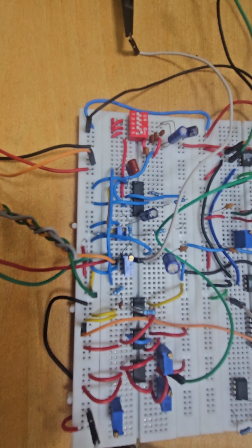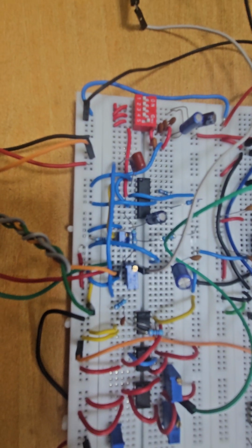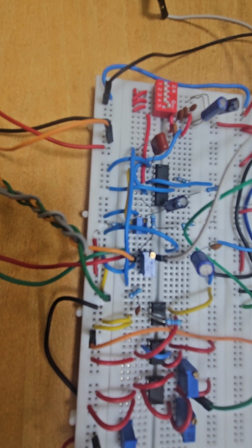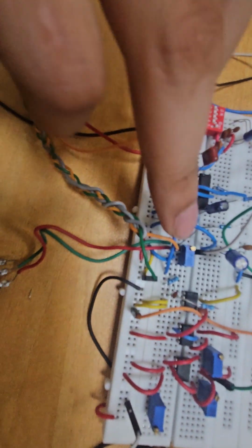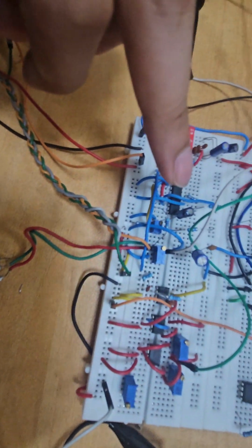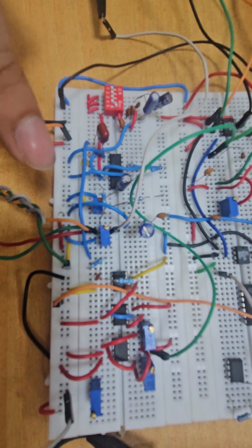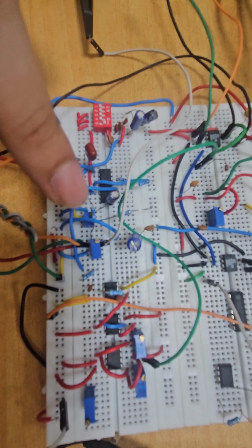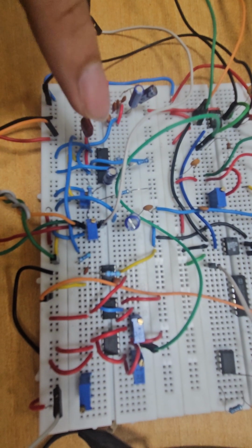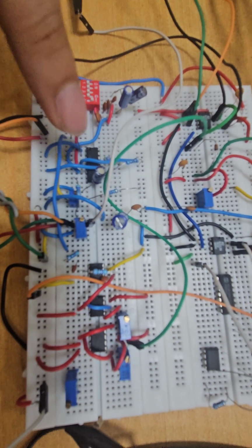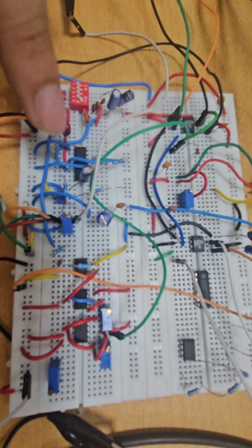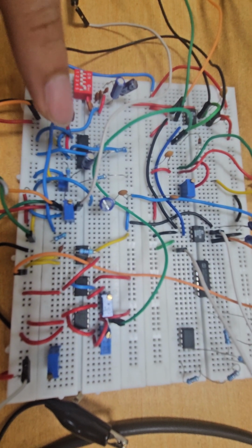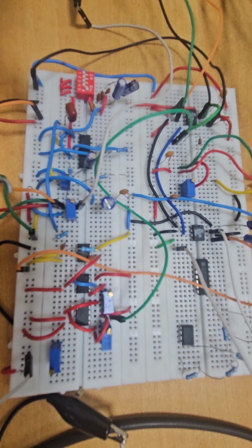Also at the pin number 7, I have one potentiometer which will vary the current going into the pin number 7, which shifts the carrier frequency. So if I add my voltage signal m(t) here, that will lead to change in the current going inside the pin number 7. So my instantaneous frequency will change as fc plus kf m(t). If my m(t) is 0, then it will set a fixed frequency, that is the carrier frequency.